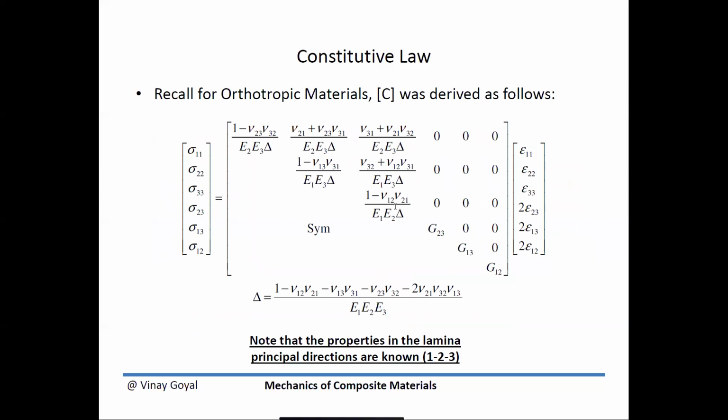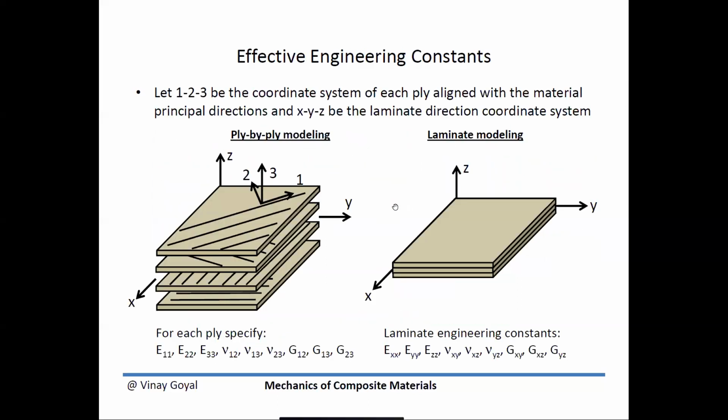Now, what we want to do, though, is somehow transform the constitutive law that's aligned with the principal material orientations to the laminate system. So then we can later come up with an approach to getting the effective laminate stack properties.